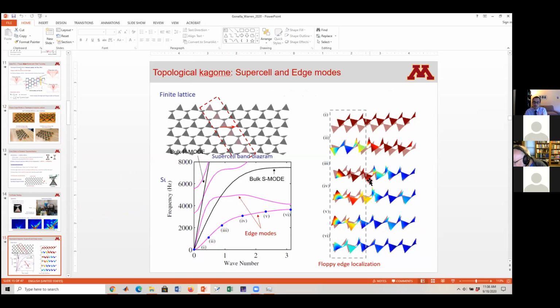Now, this is a property that should be independent of the size of the supercell, so essentially how long the strip is. I would say that having a longer supercell would only make you appreciate this better, because if I have an attenuation within a finite number of cells that is not too far from the number of cells that I have in that direction, I might not even appreciate the attenuation very much. Instead, if I have a large number of cells in this direction, I still attenuate at the same rate in space, and then I have a large number of cells that experience zero deformation. So I would say that the only difference in manifestation would be how dramatic the localization would look.